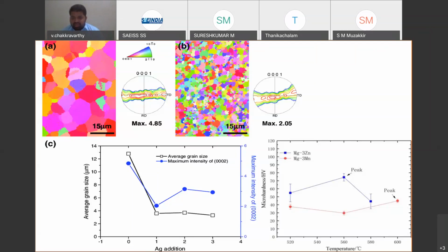Based on the Hall-Petch empirical relationship, a finer grain will always have better micro hardness, and if the micro hardness is very high, then the material will have high wear resistance properties. So obviously fine grains are more preferable for wear resistant applications. If you are not concerned about wear, and are concerned only about corrosion resistance, then coarser grains are preferable, and that too with a triple orientation, especially for FCC metal. For FCC metal, only the triple orientation gives the best results. But for HCP metal, the 0001 orientation of grain growth is more preferable.